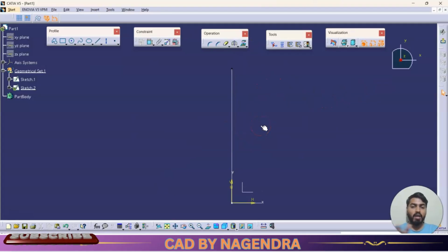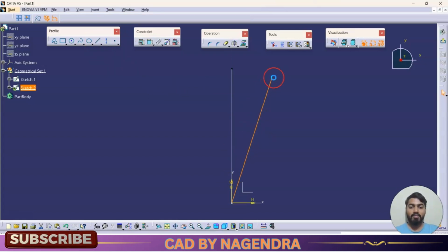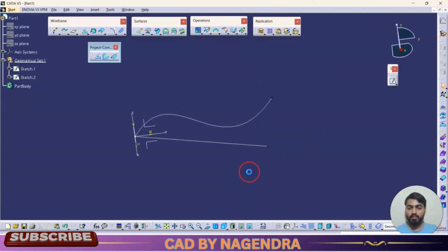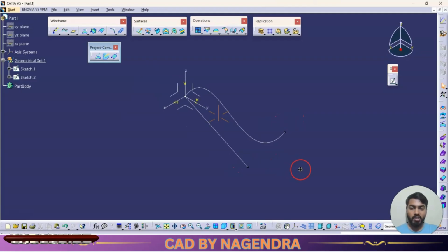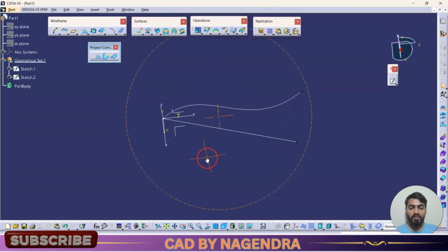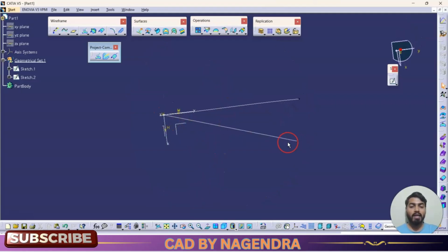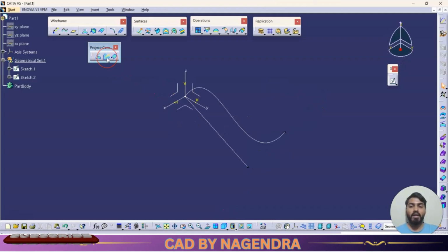in front view we have a spline. If you see from top, it will be a straight line, right? But what I want is an inclined shape, like this. So any shape, if I see from front view, I need a spline type, and if I see from top view, I want it inclined. In such a condition, we can use this Combine option.